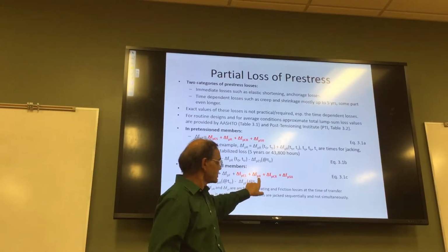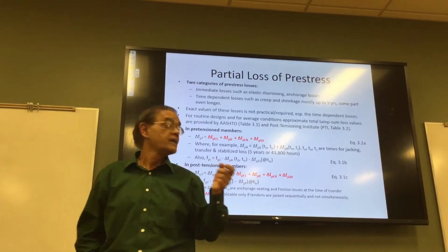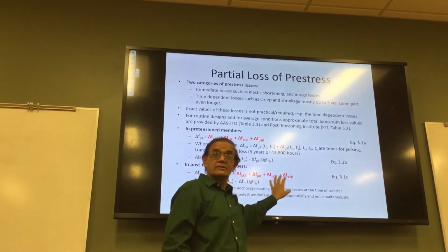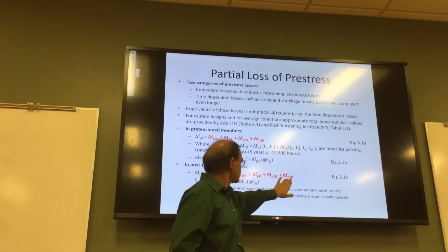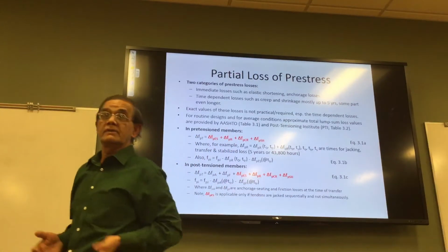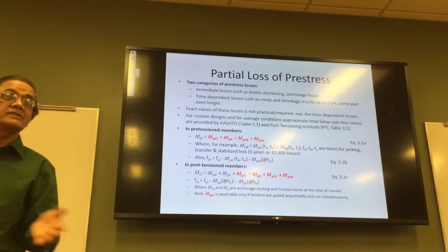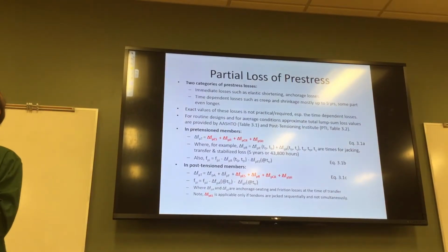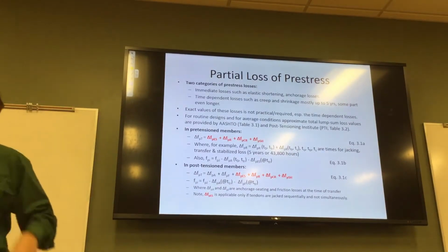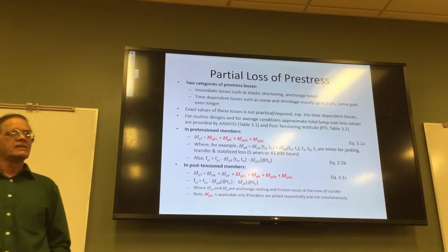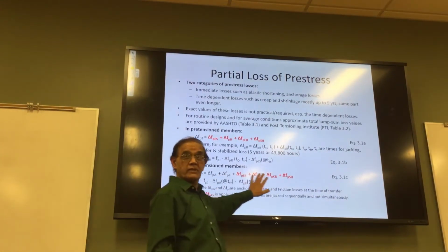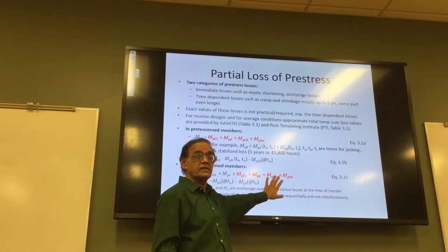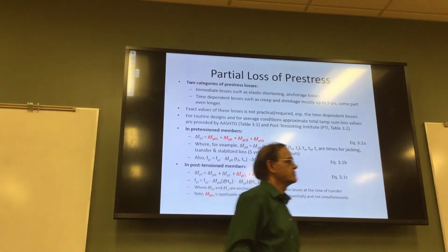And relaxation, of course, starts kind of late. And all these start late. The difference is that the shrinkage and creep has already happened before you applied any stress. And if you waited long enough, like a month or two, then most of this is done anyway, right? More than half. So you have to watch out where you start, what strength you start with. Okay.